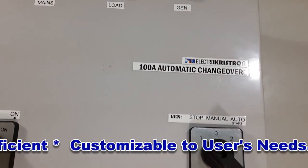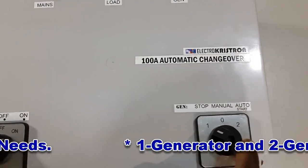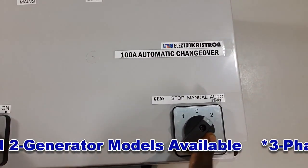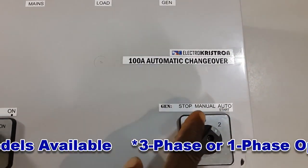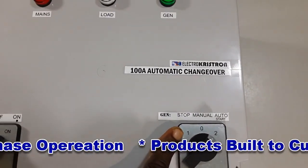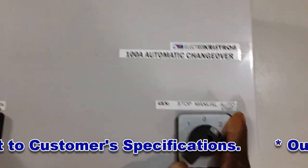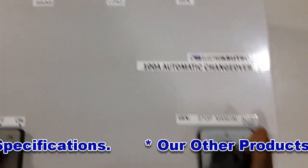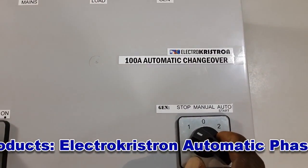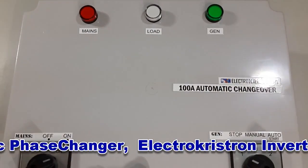Ordinarily, your generator should stop as soon as public mains is restored, irrespective of the position you have set this switch on, whether in the auto mode, in the manual mode, or in the stop mode. Of course, in the stop mode, your gen will not even be running in the first place. But if you put it in the auto start mode, it means your gen must have started automatically when power failed. Now, if you have to stop it, you either stop it by yourself manually, or the gen stops automatically as soon as public mains is restored.